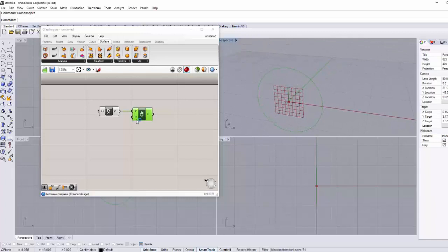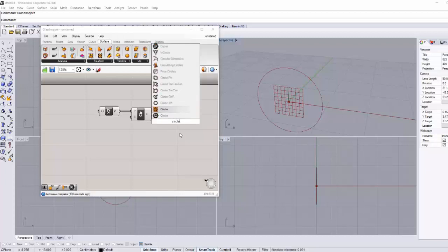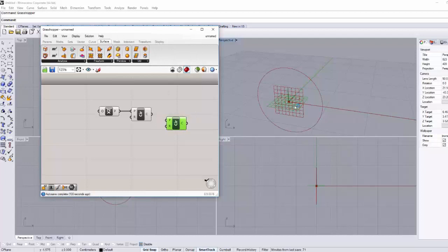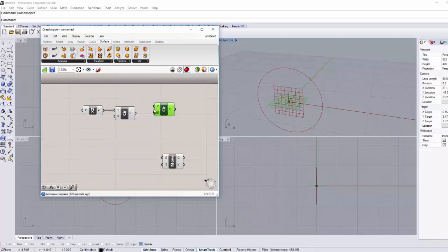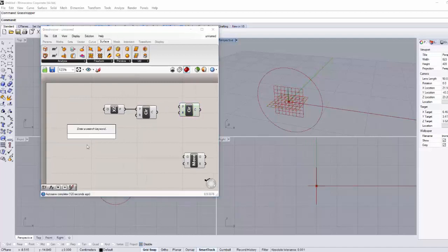That's the good thing about Grasshopper, you can customize the size very easily because the whole formula works together. So the tree ring, how it's gonna look like. We're gonna put a circle above but lying in this plane XY. So we're just gonna have to use the command move, and this circle we want to give also the same radius, so 2 times click.